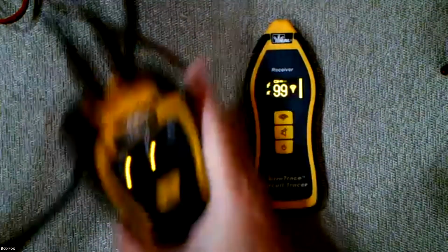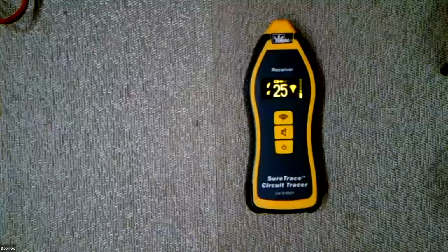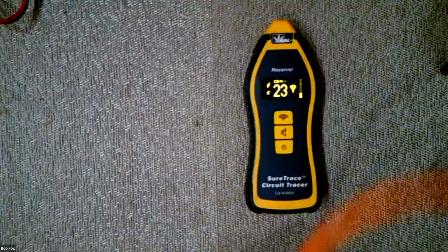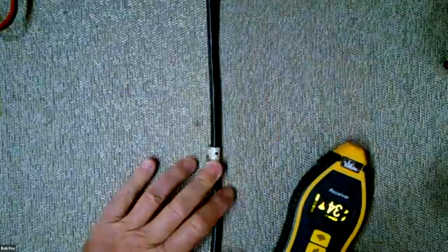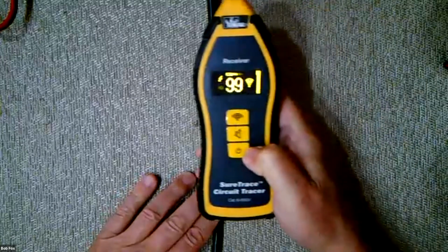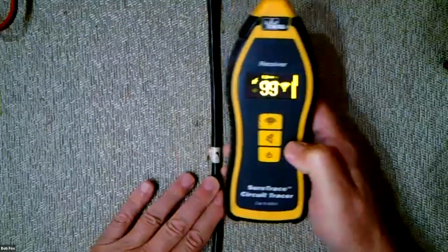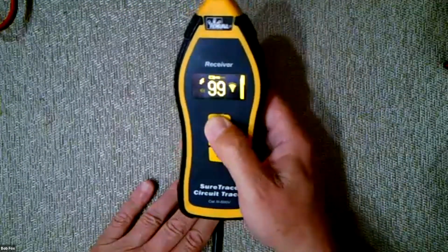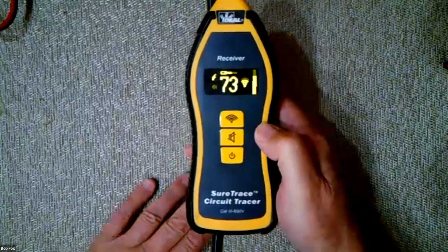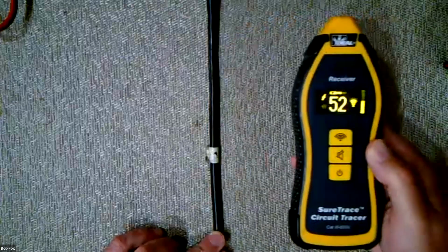Now, I want to arrange this in such a way, if the transmitter is too close, you can't demonstrate it because the signal goes everywhere. So I'm just going to bring up some extension cord here. So we'll lay this down. I'm going to turn the sound back on. Now we're in the highest setting right here. So obviously people say, well, what do I start in? I tell people just start in the highest setting. If it's 99 everywhere and you can't tell what's going on, step it down a step. Okay, so now if you could imagine that the wire itself is behind a wall, for instance. So we're going to come in from the side.